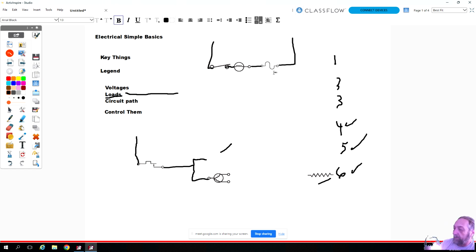We need to find out, if this fuse went bad, why did that fuse go bad? Was it a thermal fuse because the temperature got too hot, or was it an amperage fuse where it got too much amperage? But if you run across like the Whirlpool dryer and you got a thermal fuse on that motor, and you change the thermal fuse, you most likely didn't fix the problem, even though the machine's running.